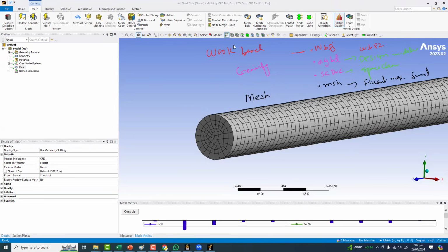We have the lines here, and these lines will have the XYZ coordinates. On these coordinates we are going to solve our equations, and we have to find out the values maybe on this cell center. This cell center will be on the whole volumetric cell. Okay, I am talking about this 3D volume element, and we also have one edge inside as well. So on this volume center, we have one node.